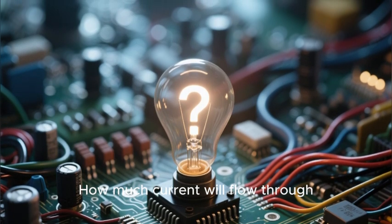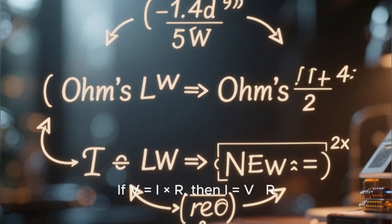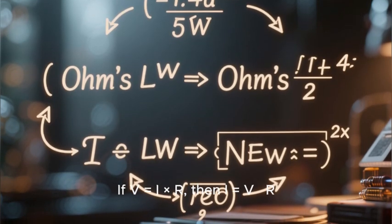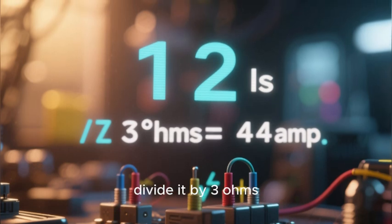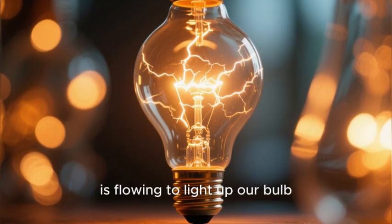Suppose you have a simple circuit with a 12-volt battery and a light bulb that has a resistance of 3 ohms. How much current will flow through that light bulb? We can rearrange the formula to find out. If V equals I times R, then I equals V over R. So, we take our 12 volts and divide it by 3 ohms. That gives us 4 amps of current. That's how much electricity is flowing to light up our bulb.